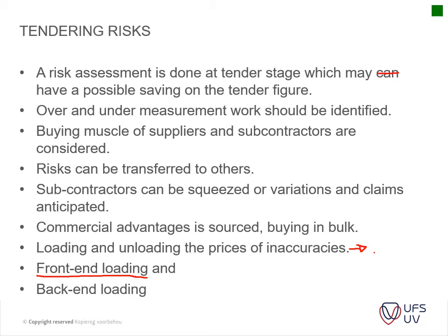So please note that this is a very risky item, and the QSs usually pick it up when you do your leveling of your rates before you get appointed. And then obviously you get your back end loading, where you load some of your items at the back of your project. That might be, for instance, your finishes, etc.